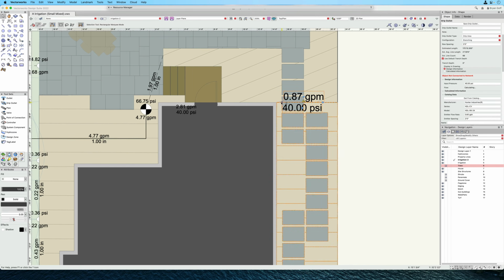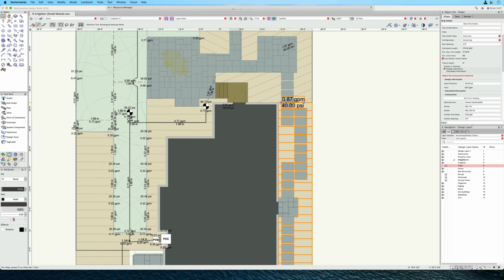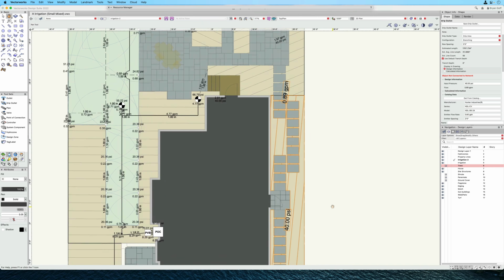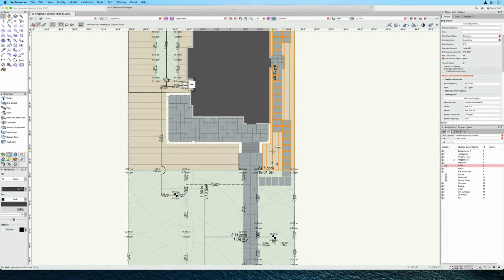I usually don't. We have a connection point. That's where we're going to connect to with our valve. In this case, I'm going to move that connection point all the way down below here. I'll put it right smack dab in the middle, and then all my lines get crazy. That's because on the other side, you're going to see the direction point. That allows me to set a direction of how I want this pipe to move. And I want them to move linear in that direction. You'll also notice that once you do that, you may recalculate or use a different amount of pipe.